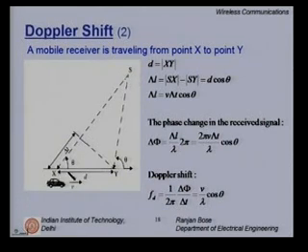So we can find out what is the delta L, because here is the location of my source. So when it moves from here to here, the signal which was coming in this direction translates to here, and you first calculate the change in the phase of the received signal, which is given by delta L over lambda times 2 pi. Use basic geometry and you can calculate that the frequency shift because of Doppler is nothing but 1 over 2 pi delta phi over delta t. Rate of change of phase is v over lambda cos theta.